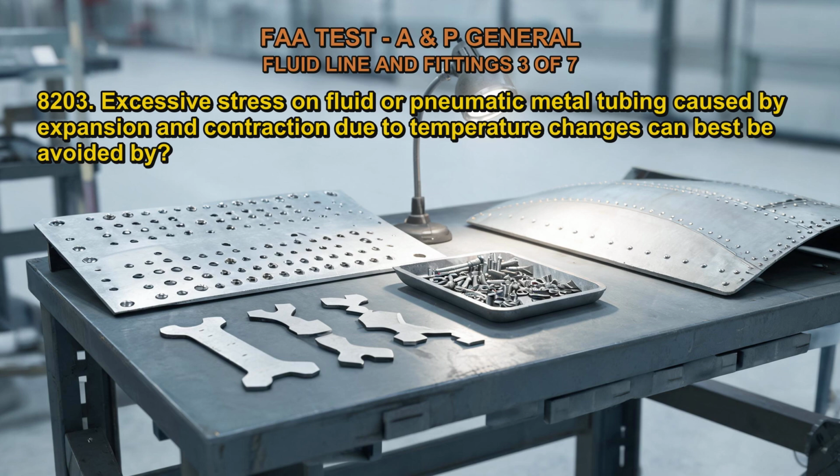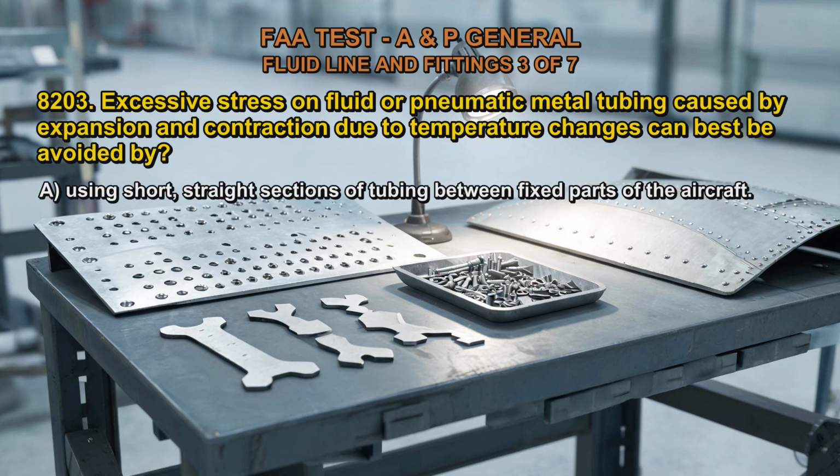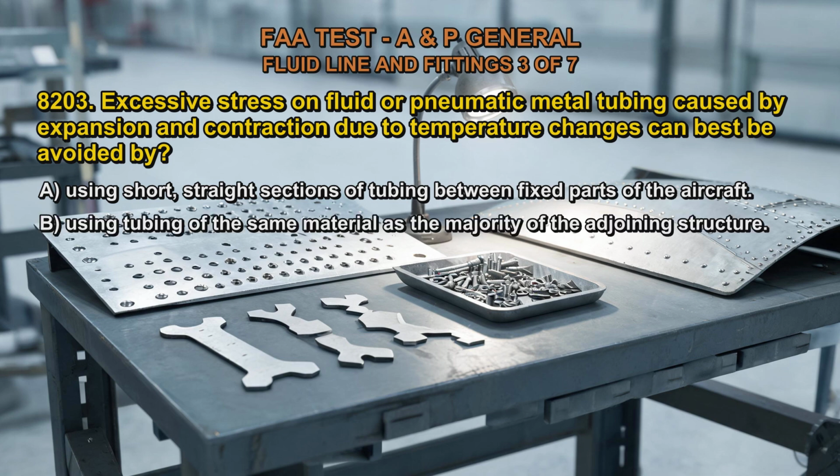8203. Excessive stress on fluid or pneumatic metal tubing caused by expansion and contraction due to temperature changes can best be avoided by A. Using short, straight sections of tubing between fixed parts of the aircraft. B. Using tubing of the same material as the majority of the adjoining structure. C. Providing bends in the tubing.